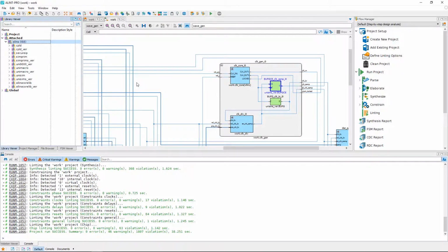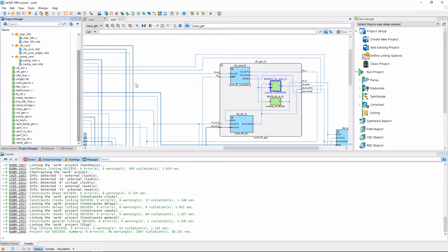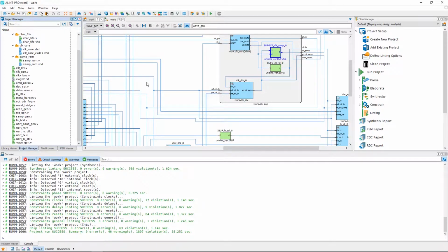Also, there is no current support to work with UCF constraints. It is best practice to create a chip-level Aldec design constraint file and bring over the necessary constraints. You can check out our tutorial video on chip-level design constraints to learn how to create or automatically generate constraints. Keep in mind this step would be for advanced or non-obvious cases when linting a design. Automatic detection of clocks, resets, and I/O delays works fine in most simple cases.